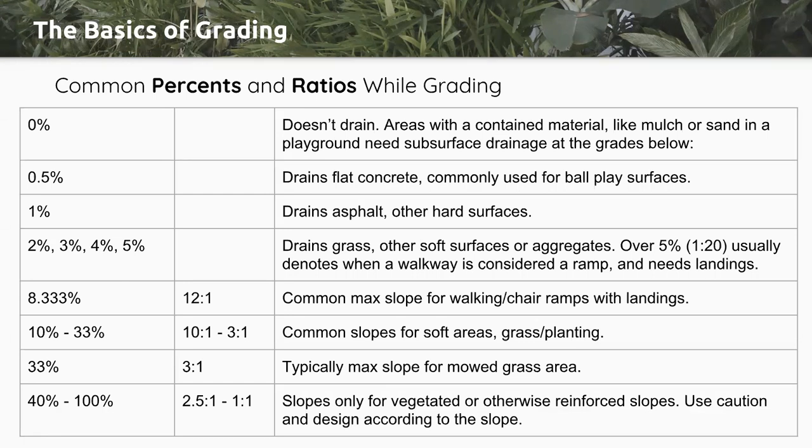And then as we go further down, you'll see what percentages drain concrete, asphalt, grass. And then most notably, once we get over 5%, we're really getting into a range where safety comes into play quite a bit, especially with accessibility standards in your local area. So for instance,